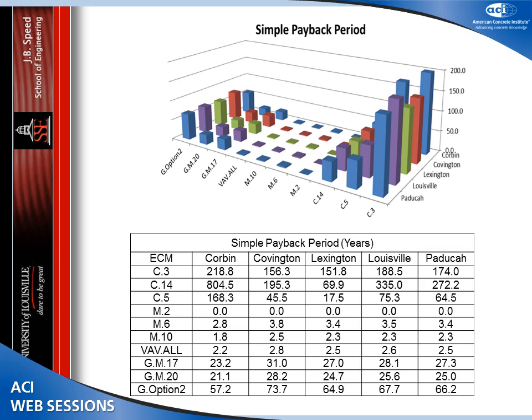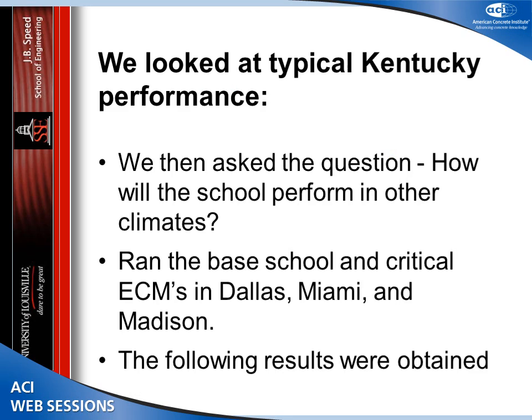Interesting to note, these geothermal heat pumps give 80% energy reductions, but typically your paybacks are in the 20 years plus. The installation of the ground loops is very expensive, particularly in our area, where we had to blast in most of the areas in Kentucky because of the limestone. Okay.